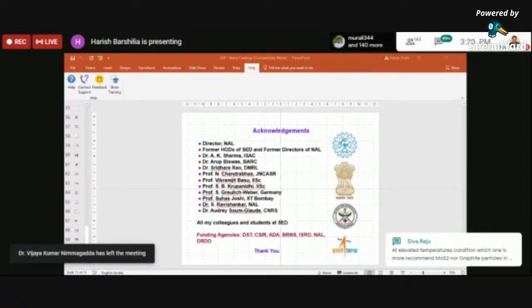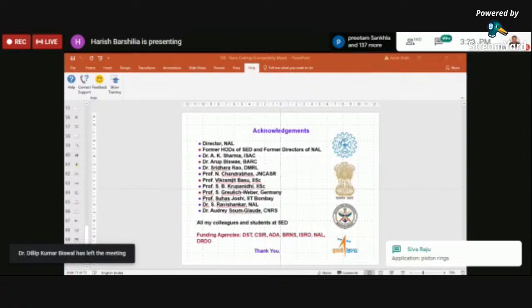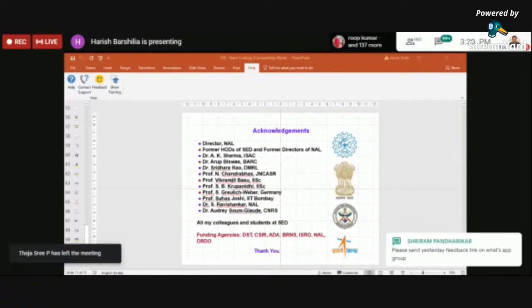What kind of nano coatings are suitable for making good heat exchangers or radiators? It's a very good question. The basic property you have to look into is that the emissivity should be very high. Most of these black materials, for example, black coatings made by anodization, or graphene or reduced graphene oxide kind of materials, will be very good for these kinds of applications. If you see most radiators, they are either white or black, because the emissivity has to be controlled.